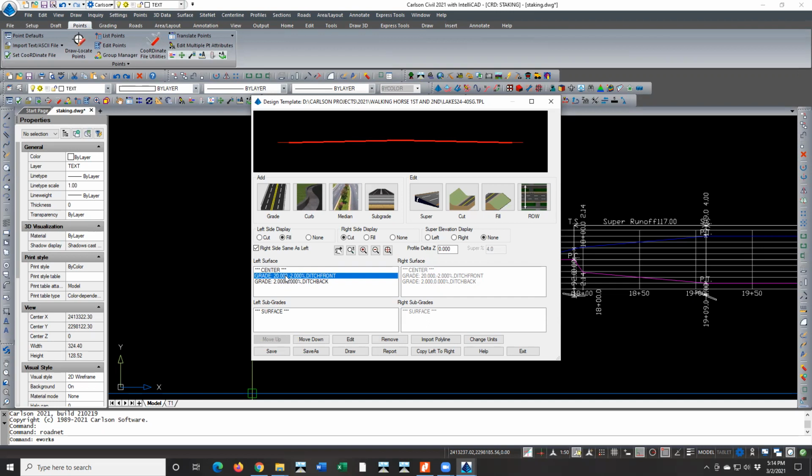The finished surface. Well, the finished grade is 12 feet, a 12-foot half width, and then a 2-foot shoulder. All right, so we're out to 14 feet. So there's 6 more feet where this keeps going. Yeah, so it's 6 feet at 4 to 1. So okay, it's a foot and a half section.